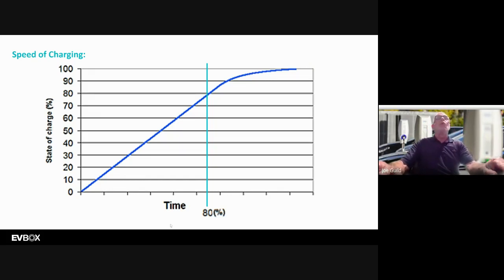And another thing to make you aware of, if you're not already aware of, is also with DC, that 50% of the charging, time-wise, covers 80% of the battery. So that means that the last 20%, when the battery's almost full, takes almost as much time as the first 80%, because of course they don't want to cram all that into it. So customers would call complaining about their charging speeds, but you'll ask them, how full was your battery? It was 75% full. Well, that's common at that state of charge, as we call it.